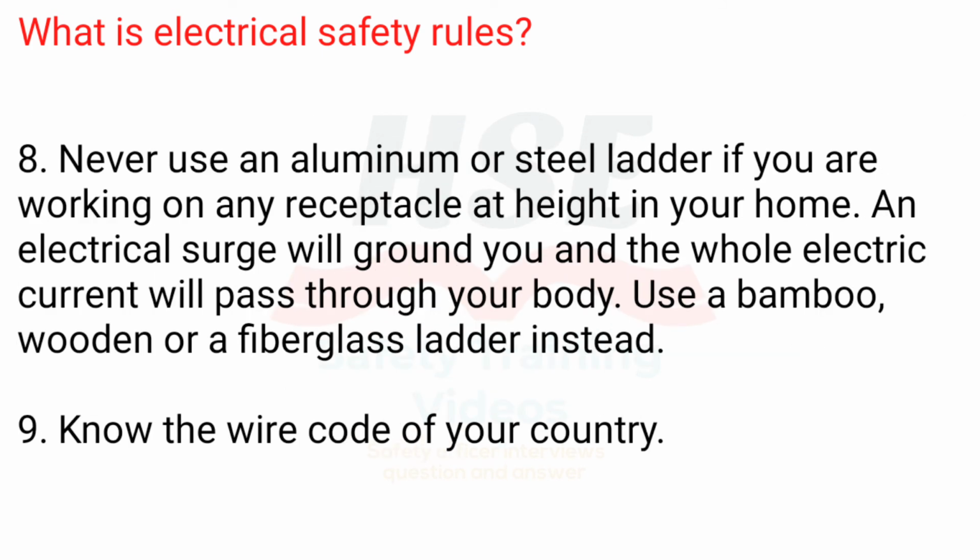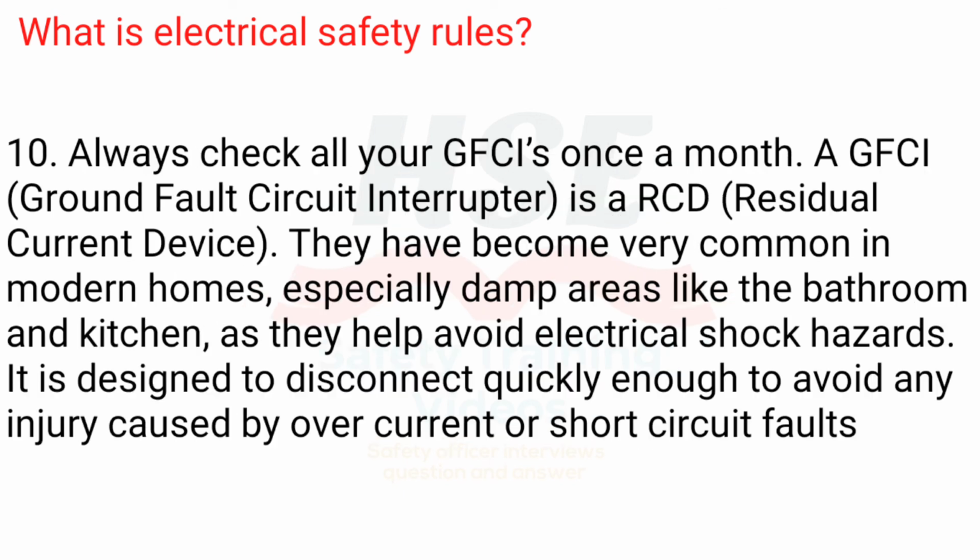8. Never use an aluminum or steel ladder if you are working on any receptacle at height in your home. An electrical surge will ground you and the whole electric current will pass through your body. Use a bamboo, wooden or a fiberglass ladder instead. 9. Know the wire code of your country. 10. Always check all your GFCIs once a month.